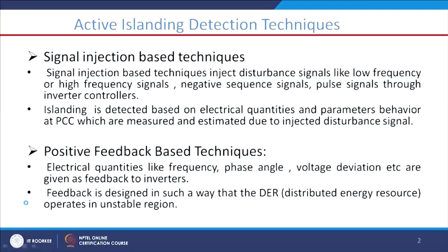So, that is why we look at another technique, the active island detection technique, and a number of techniques are available as far as active islanding detection is concerned. Also, many hybrid island detection techniques are now developed, and communication based techniques are at a very premature stage. The wide area monitoring system, PMU or micro PMU, is going to play a great role in communication based island detection.